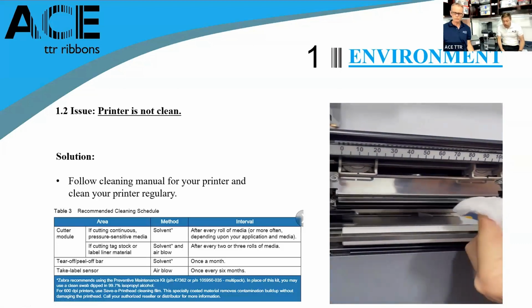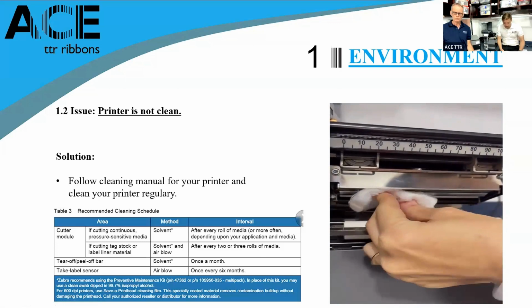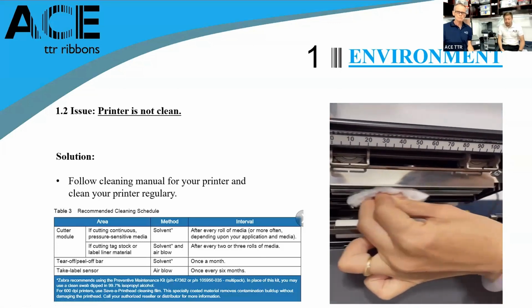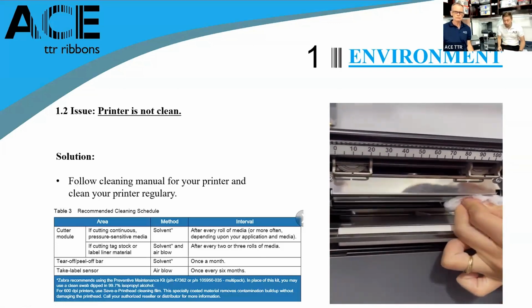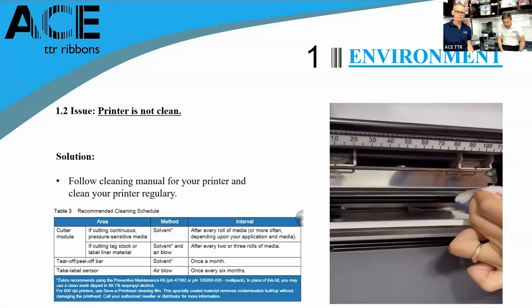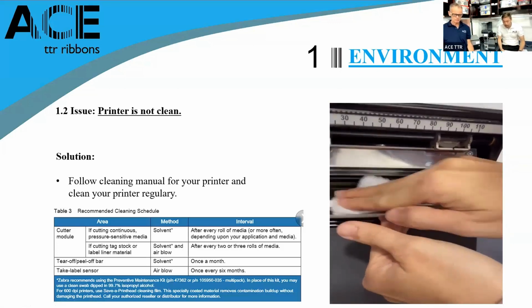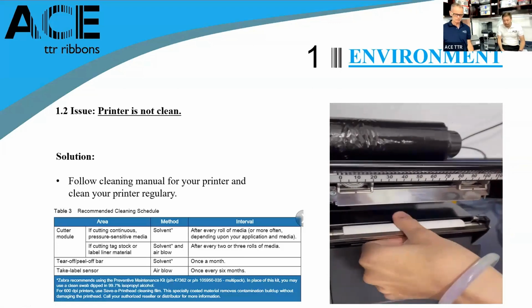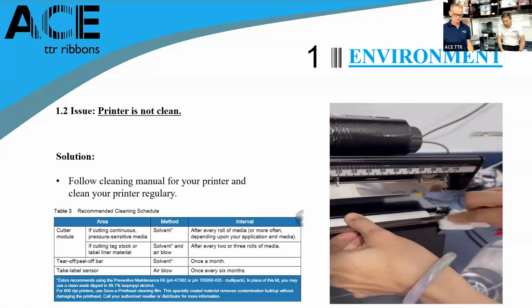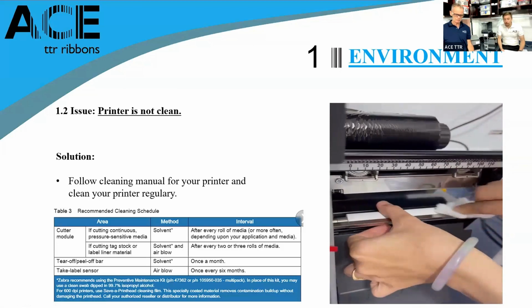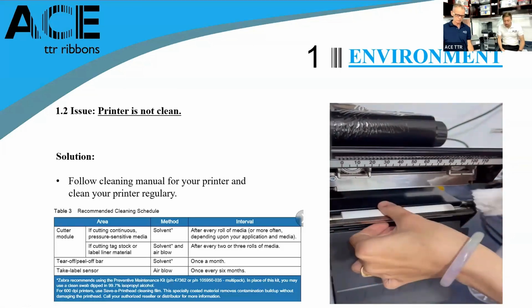We have many questions on how often you should clean your printhead, and the answer really depends. It depends on your printer, it depends on how often you print, it depends on what kind of TTR you're using as well, and what kind of substrates. But we'll definitely recommend to clean it at least once a day, and it's best to do it at the beginning of each production shift.